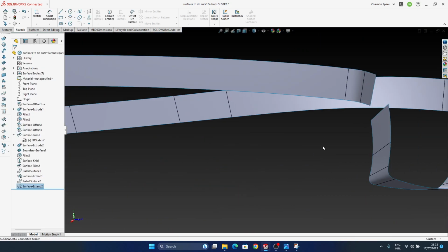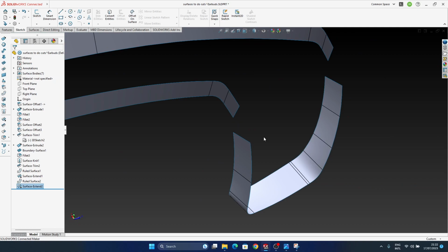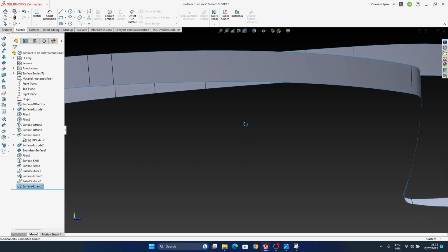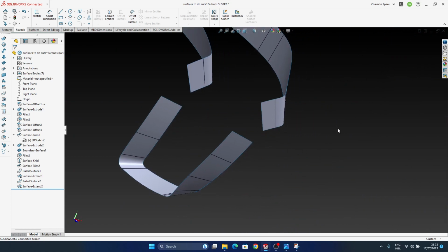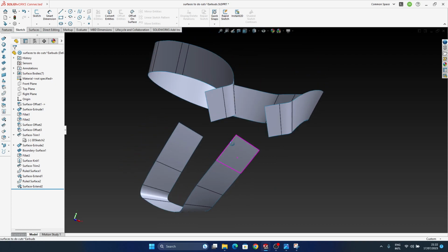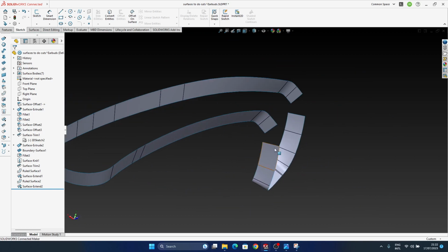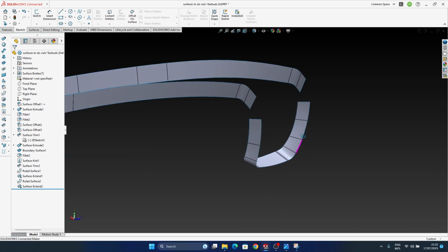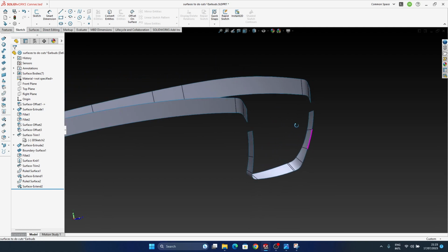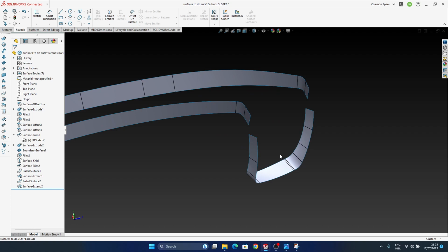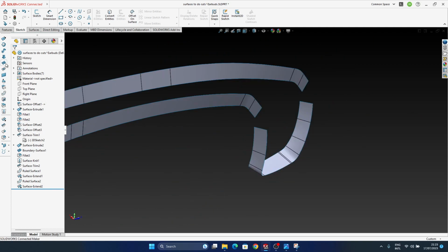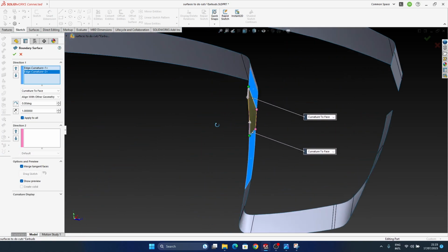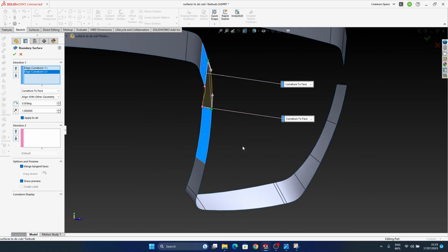So why I want to do this is because when you start to make the cuts, you will need to have a bit of space in between the cuts. And the last thing you want is to make the same surface all over again. So make something similar to this. And also, why it is so important to make it starting from the surface using a ruled surface is because when you start to combine these directions, you will never end up at 90 degrees at that point on the surface. So then it becomes very, very difficult to actually make the cuts look all right. I mean, maybe it will look kind of all right, but only to some degree.